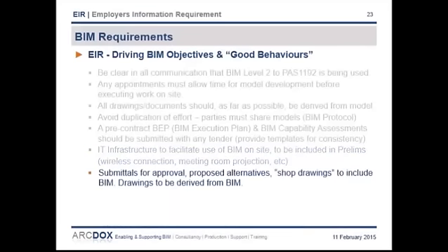You want to make sure that the normal submittals and approvals process includes for providing BIM. Otherwise, you'll find that subcontractors simply provide quick 2D drawings to get approval without really resolving anything and then produce the BIM much later. You want to test submittals and any proposed design alternatives in the model before approving them.